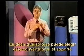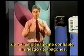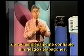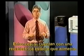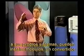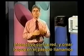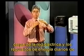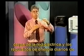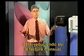So a choice of a true utility interactive inverter would only be made in those cases where you have a reliable utility grid. Not appropriate to have a utility-dependent system where you've got brownouts and blackouts threatening you. But in cases where you have a stable and good utility system feeding into your system, you can install modules and a utility interactive inverter, and create what we called in the past demand-side management capabilities, where you were able to reduce the load that is seen by the utility, and you reduce your daily energy requirements from the utility, thereby reducing your monthly bill.